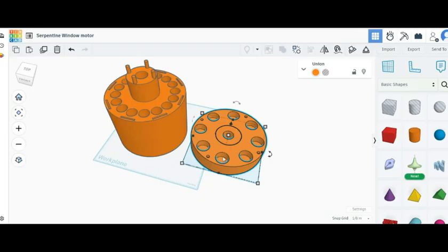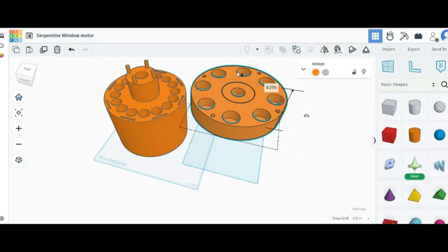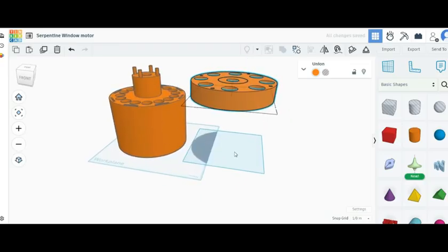So in other words, this is also going to be where you put a generator coil there or there. You could put 4 or 5 of them in, but you have one slot empty, and that's where you put the Hall effect sensors. So this is where you put generator coils, and it's also your timing wheel for this, so that you have a place to put the Hall effect. So let me just move this up and see if we can look at how it'll be when it's put together. And you have to do it in 2 parts like this, because otherwise you have an overhang. You can't just print off the edge of the cliff. It ends up like Wile E. Coyote.